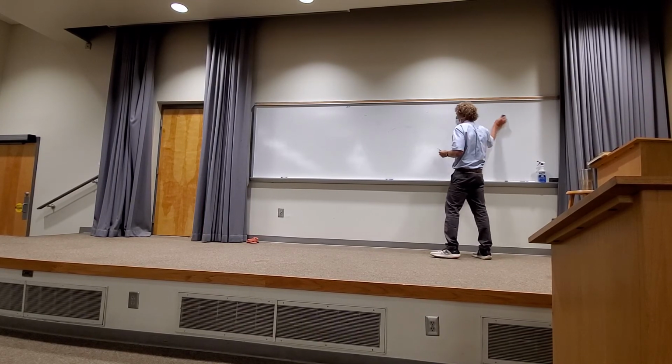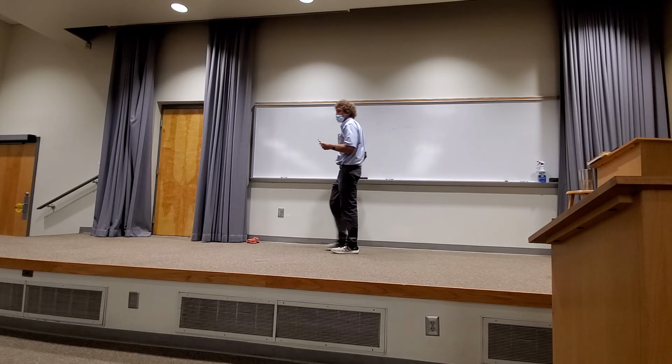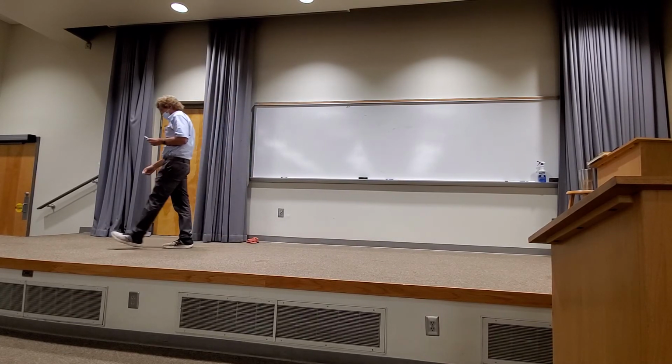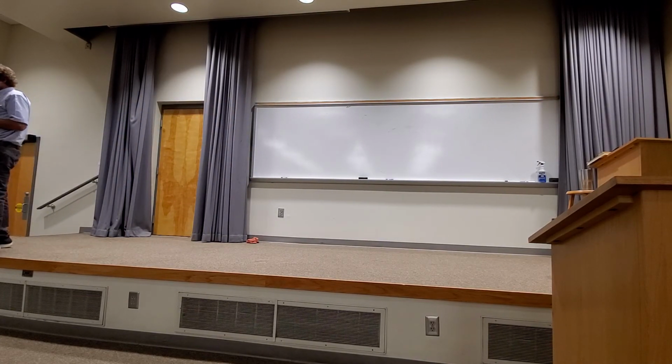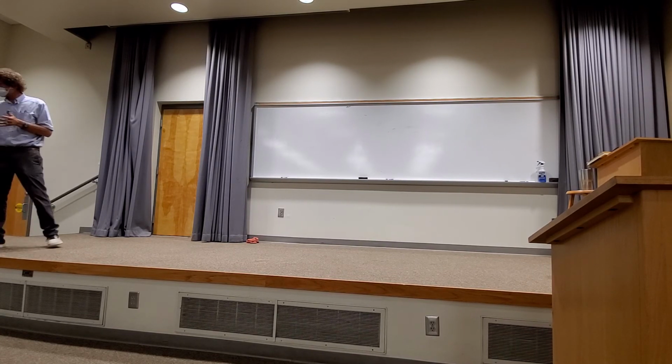Excuse me, sir. Go ahead. So in the previous diagram, you said V1 minus VR1 minus VR2 minus V2 equals 0. So how do you assume that current flows from V1 to V2? Why did I assume it? Because that's arbitrary. I did it in my mind, but you can assume current in any direction. Now, the final value of current, if it was assumed in, let's just call it the wrong direction, would have a negative value. It will always come out in the wash, and you'll see that.